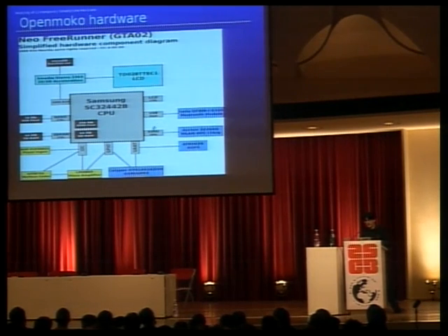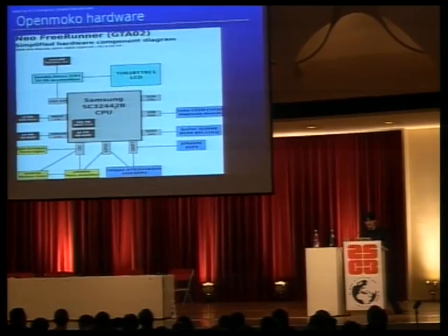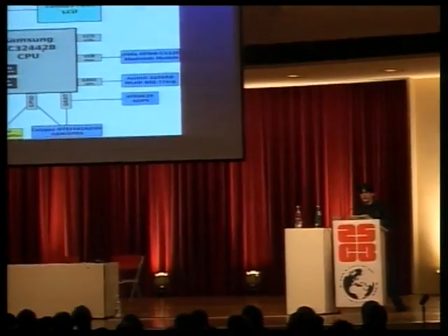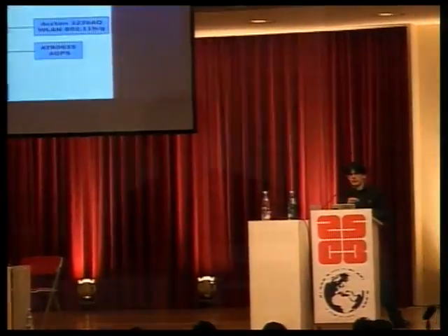So this particular component is one component that is 13 by 13 millimeters, and I think maybe 1 millimeter in height. I don't remember exactly. And in that single package, there is not only the system on a chip, but also the flash and RAM memory. It's what's called a multi-chip package. So you have multiple dies inside one physical package to save physical, what's called PCB footprint. So you save space on your board design.